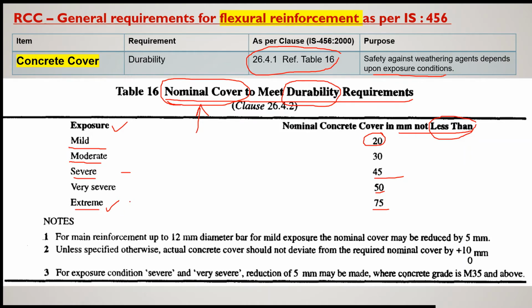Now, the very first step is to use the specified cover for the reinforcement, and then other factors are also considerable. But before that, we can assure that if reinforcement is given sufficient cover, and not only cover, type of concrete, density of concrete, grade of concrete, all these parameters directly affect the durability.